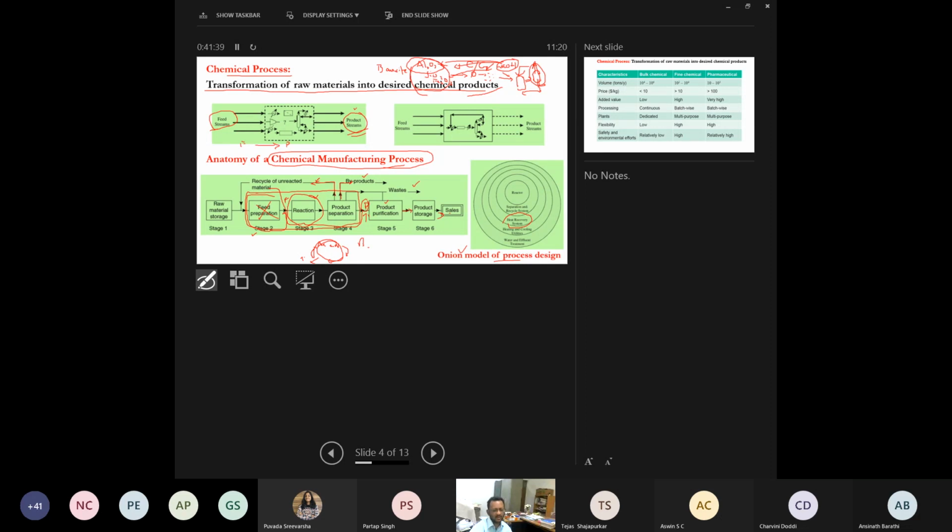Once you recover the waste heat available from the process streams, automatically we can minimize the utility requirements, whether it's a cooling utility or heating utility. The heating utility normally will be hot water or steam, or thermic fluids like Dow chemicals, Dowtherm, different things are there. Then you can use hot flue gases, or electrical heaters. Sometimes you can use molten metals.